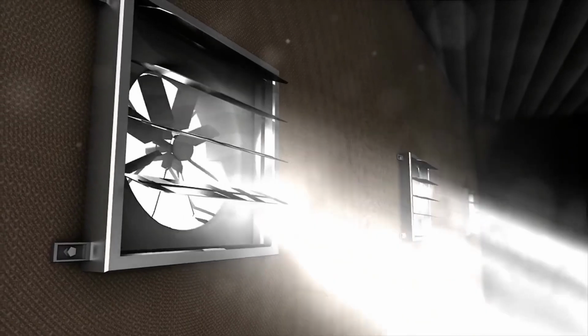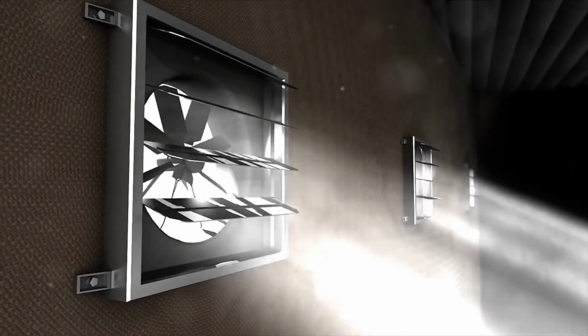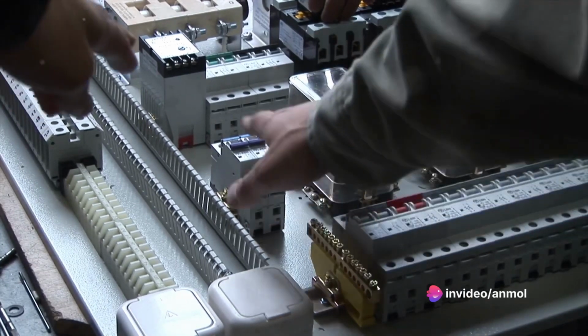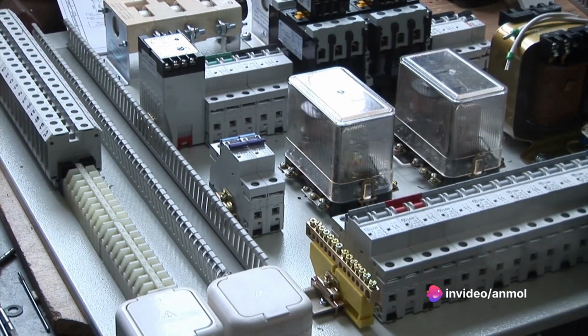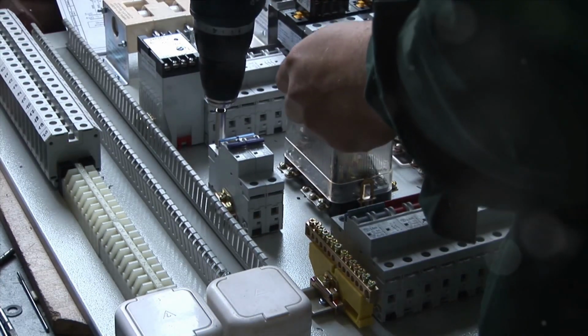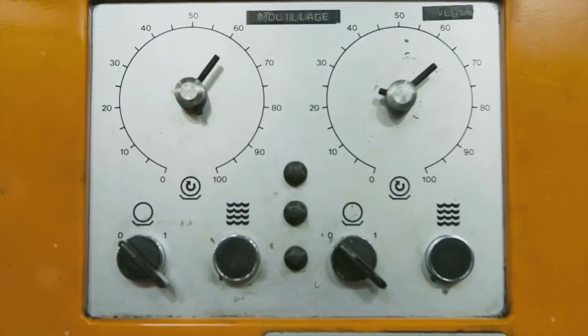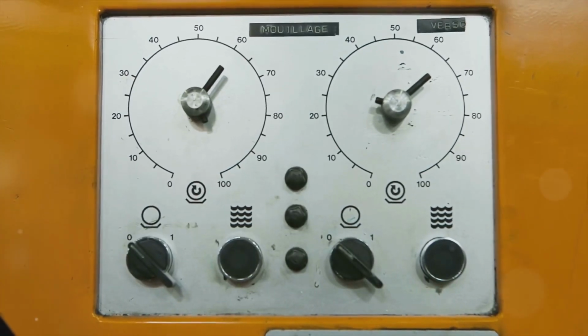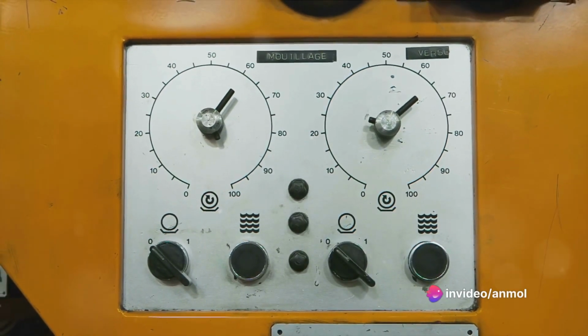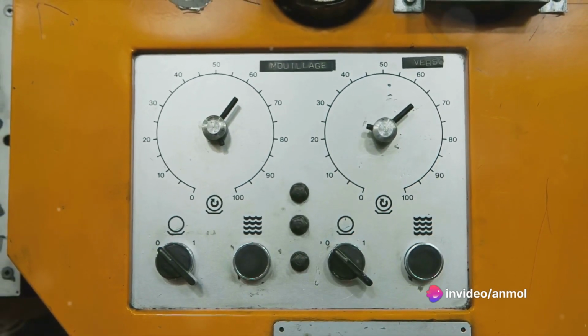And that brings us to the inverter. This is where the real magic happens. The inverter takes the steady stream of DC power and flips it back to AC. But not just any AC. This is AC with a variable frequency and voltage, which is the key to controlling a motor's speed and torque. So to sum up, the rectifier converts AC to DC, the DC bus holds and smooths the DC power, and the inverter converts it back to AC.